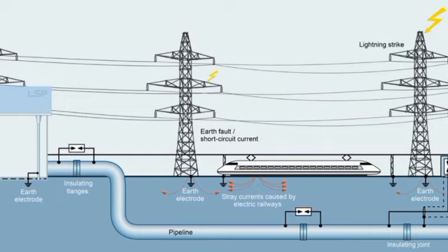For lightning arresters, the nominal discharge current is defined similarly. However, these devices are designed to handle much higher surge currents than surge protectors due to their typical application in high voltage power systems. Therefore, the nominal discharge currents for lightning arresters are significantly higher than those for surge protectors. To summarize, while surge protectors and lightning arresters serve similar purposes of protecting electrical and electronic equipment,